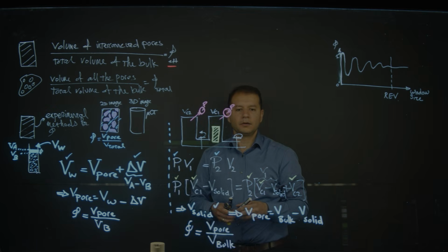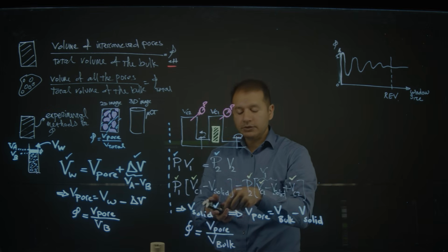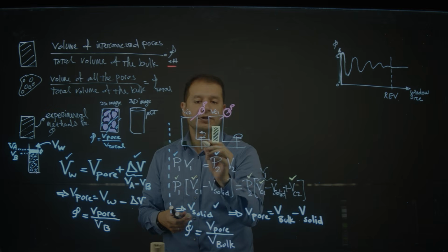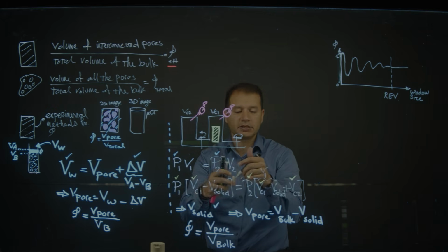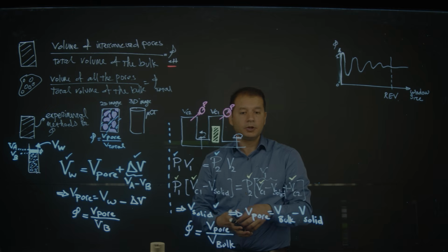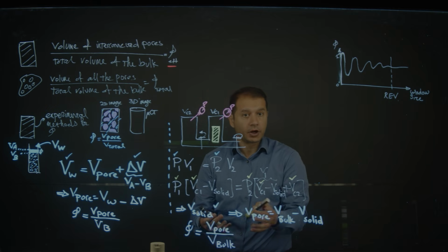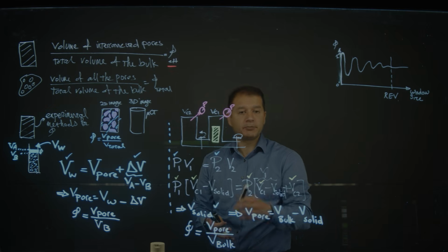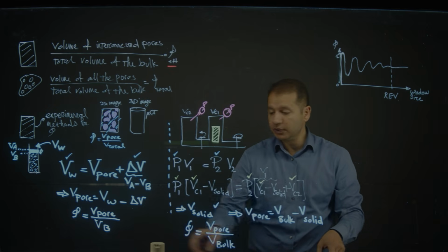Fantastic. This is gas law, which is extremely convenient for me to analyze and understand. If I have these chambers, obviously I need to fabricate the system well so that, for example, the volume of these parts in my pipes, etc., is considered properly too, or I make them extremely narrow. Now, this is a great way to understand and measure porosity, which is based on thermodynamic law. You can have many other ways to calculate your porosity.